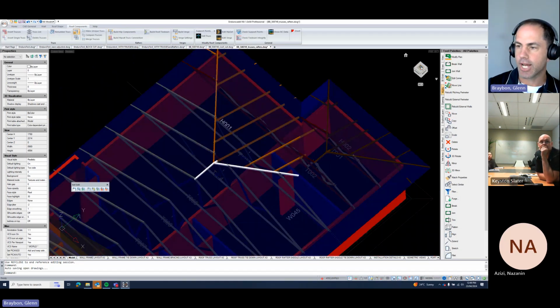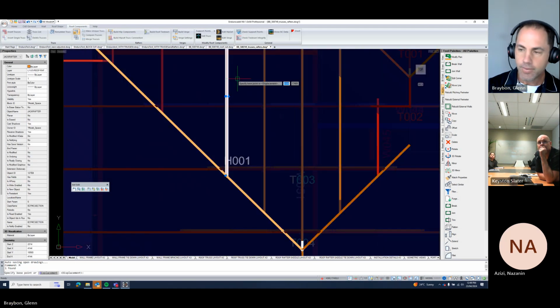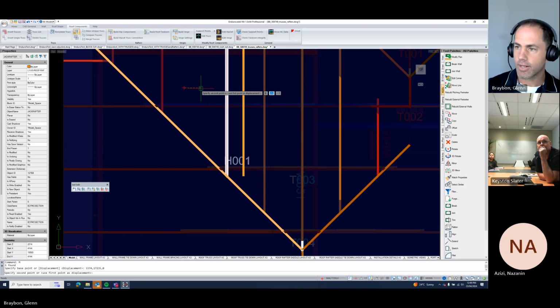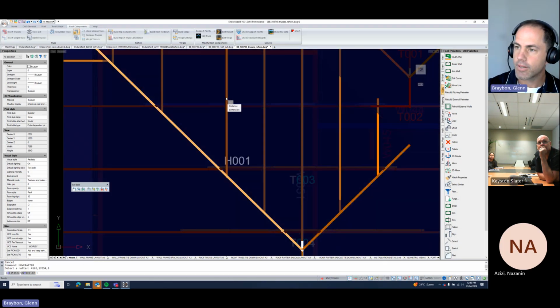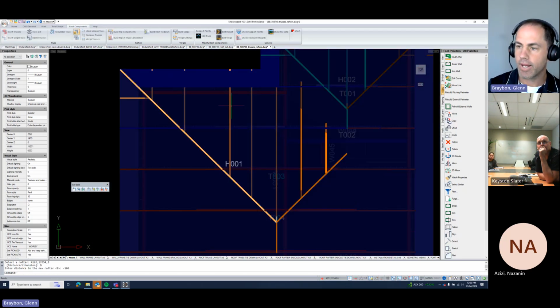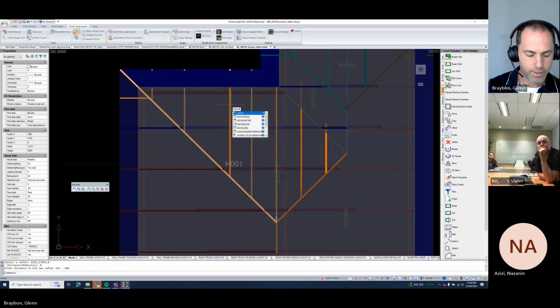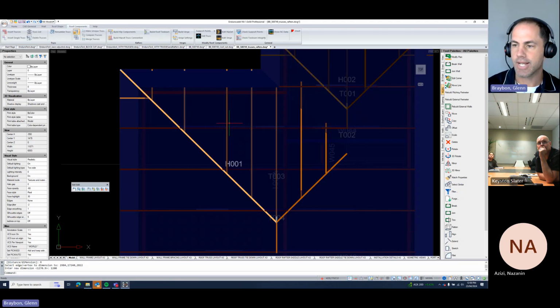But for me to make any changes, I can left select the rafter. Maybe I want to move it. Is it move rafter, Naz? Yeah, move rafter by distance. We're going to go minus 100. And it'll move it in that way. Or if we want to move rafter, select rafter by dimension to there. I want to go 1200, center to center, and it'll adjust it as such.